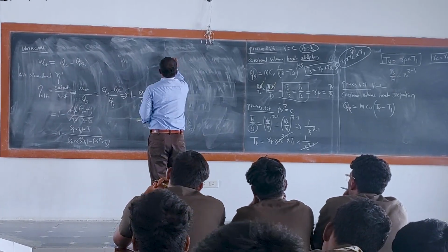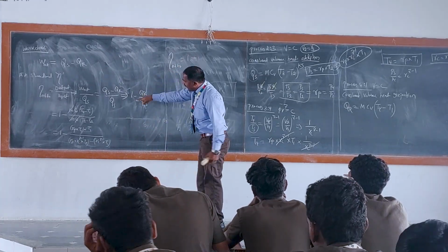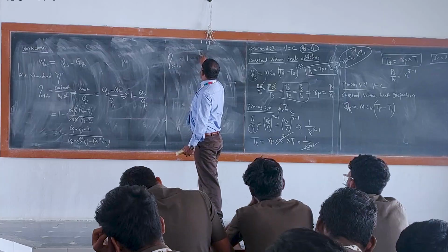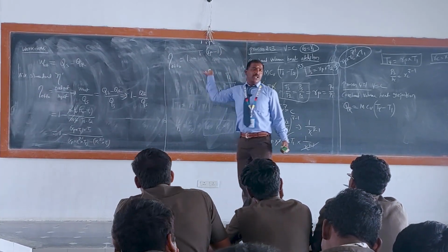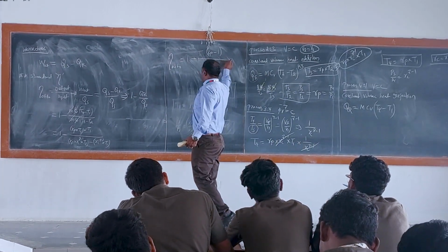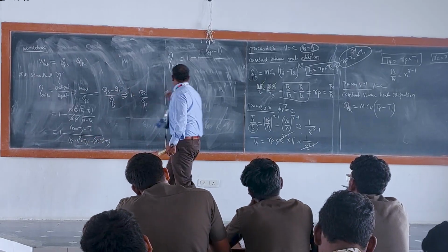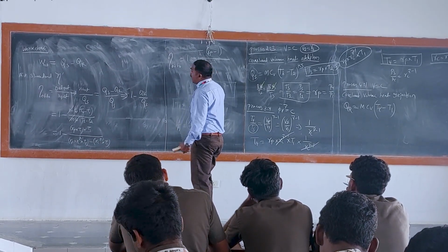So now the efficiency of the Otto cycle is 1 minus: in the top, T1 is common, so T1 (RP minus 1) outside, divided by RC power gamma minus 1 into T1 taken outside.